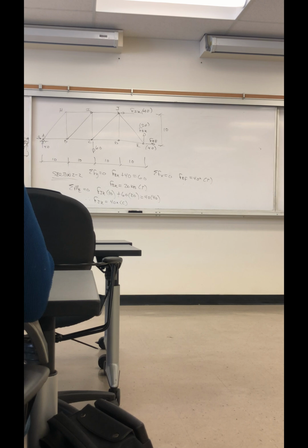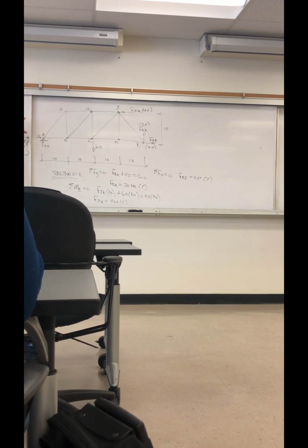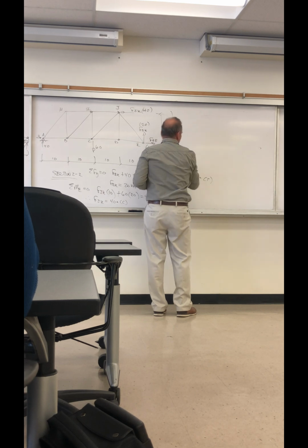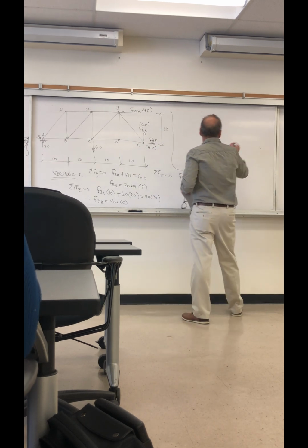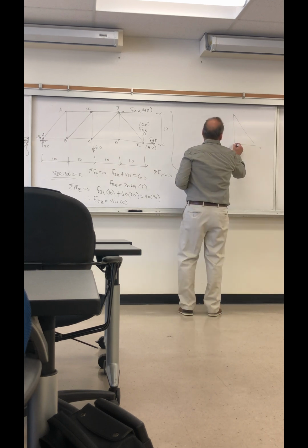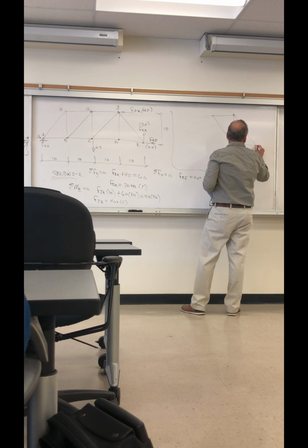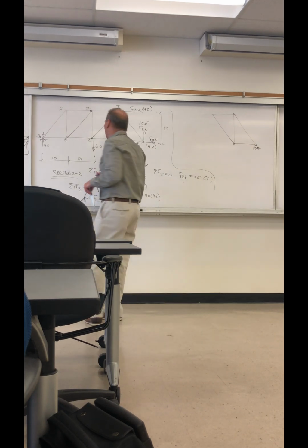Section 3.3 is a little different, so that's it for section 2.2. That's all three of the unknown member forces. Section 3.3, we took the cut just to the left instead of to the right of the points, just to the left of K and F. So in that case, we're drawing the structure that's on the right up to that. Okay? So this will be section 3.3 here. Include the reaction on that side, G, which is 20.